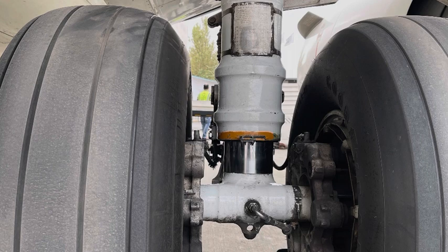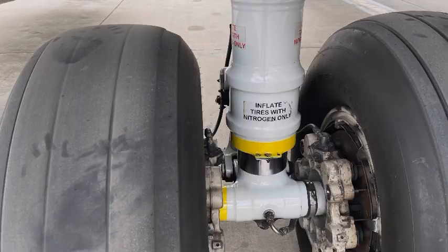It's also important to note how much the piston should be extended from the cylinder in the main shock strut, or shock absorbing part of the main and nose landing gear. To have the piston excessively extended from the cylinder is not a recommended procedure, and it will cause damage to the landing gear, mostly during the landings. So it is based on the temperature. The maintenance personnel have a scale based on the temperature. They know how much the piston should be extended from the cylinder to have normal operations.